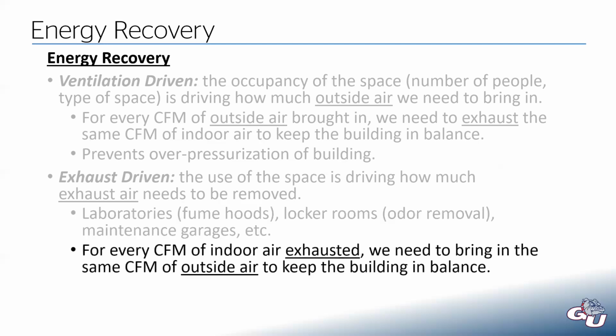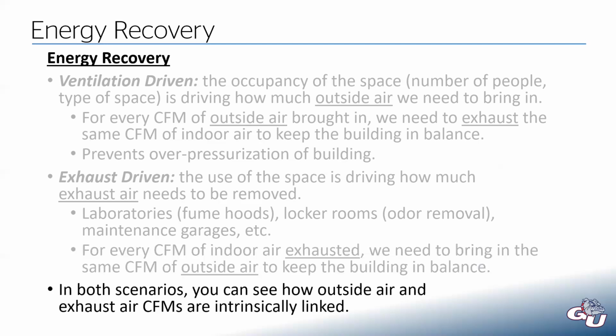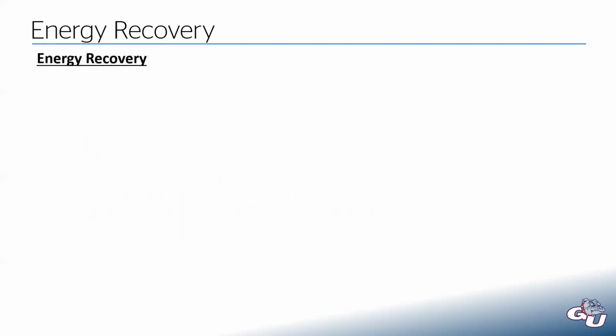And again, if we are exhausting air, now we need to bring the same CFM of outside air in to keep the building in balance and to prevent negatively pressurizing your buildings. And then you can have the opposite problem where your doors start to swing inward. But in both of these scenarios, whether it's ventilation driven or exhaust driven, you can see how outside air and exhaust CFM are linked together. If you have a lot of exhaust, you need a lot of ventilation, and vice versa. So that brings us to energy recovery.